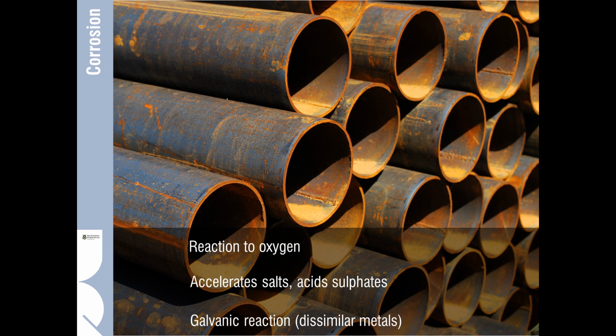The other thing that is also a bit of a problem is galvanic reaction, which is, I guess, enhanced degradation or oxidization of material as a result of the chemical reaction of dissimilar metals, and that's a common mistake made in detailing.